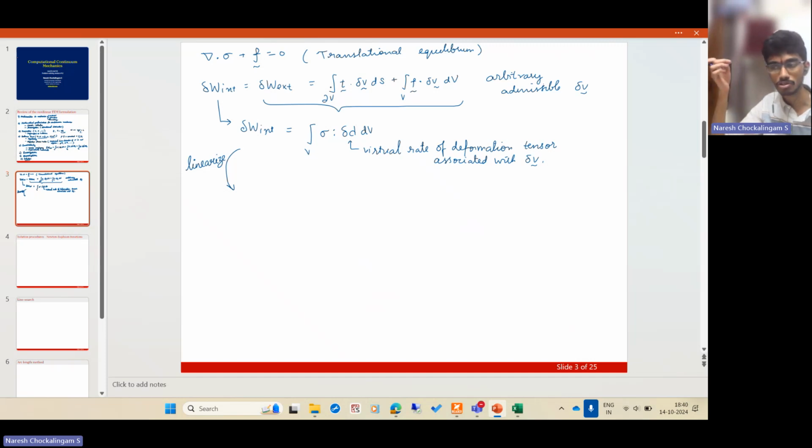So when we linearized it, we got this expression. So the linearization of the internal virtual work done about a point. So you always have to linearize about a certain configuration. Let us call the configuration phi. And the virtual velocity field is del V, right? And in the direction U. So U is a corrective displacement that will get into a Newton-Raphson scheme. Del V is an arbitrary admissible velocity field. And this phi is the current configuration.